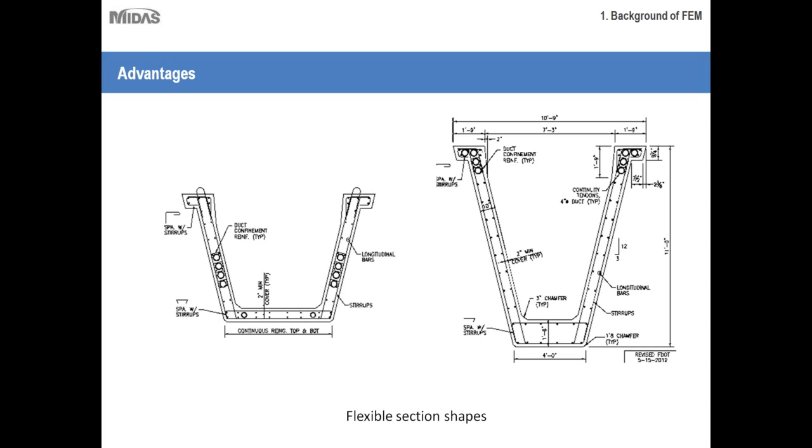And if you are doing the design check and you are planning to optimize the weight of the structure, you can consider different alternates also. Based on the type of bridge and different span lengths, you can come up with a more optimal section rather than being limited to the conventional I section that we are using.